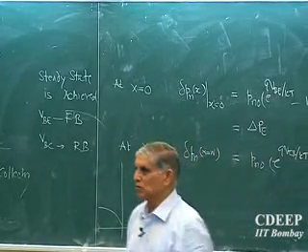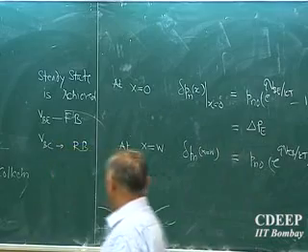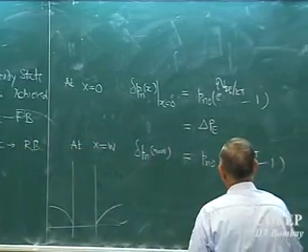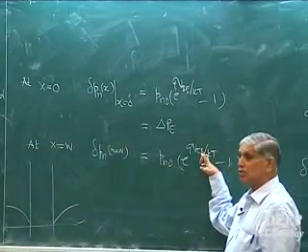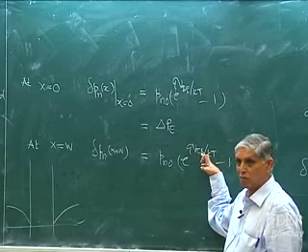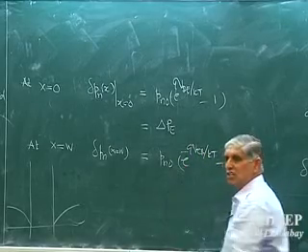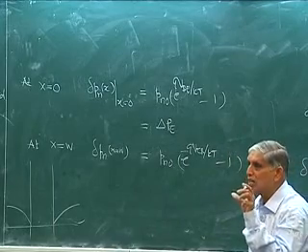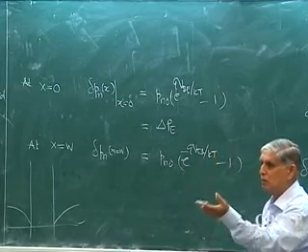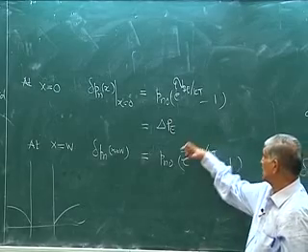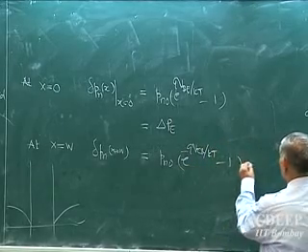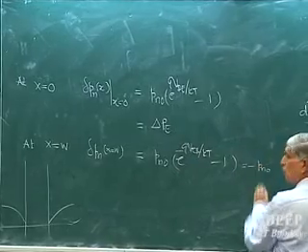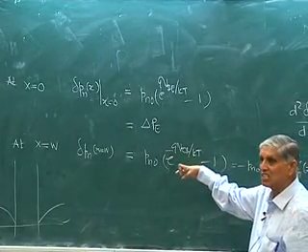They go to 0. They go to 0. So essentially what we are saying is that under reverse bias, this term is very small. Why should it be small? Because it's essentially minus qVCB. Reverse bias is much stronger in the normal case compared to the base emitter junction. So this term is much smaller, which is essentially equal to minus Pno, but this is excess carriers.